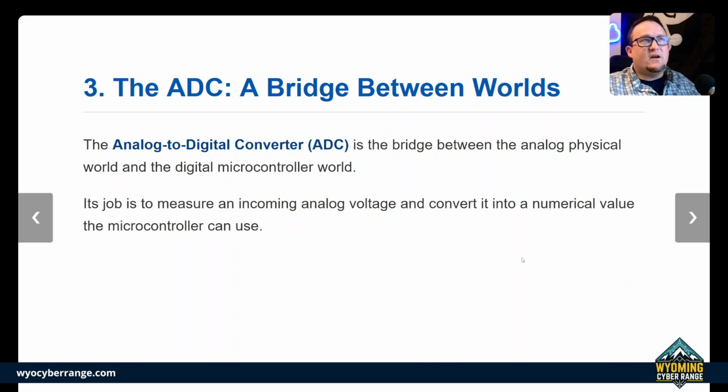Remember, we talked about how analog values in chapter 2 are always between 0 and 1023. Well, 0 to 1023 is great, but what if we're talking about temperature? The sensor is going to come back with a voltage, and then we're going to read that voltage and convert it into a calibrated number that actually makes sense to us. Maybe that means 72 degrees in our house.